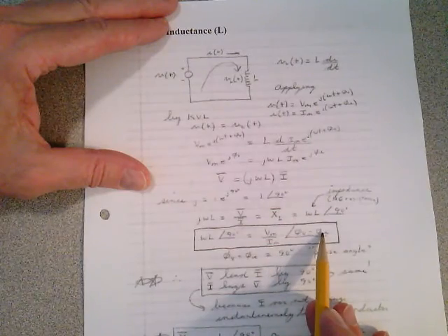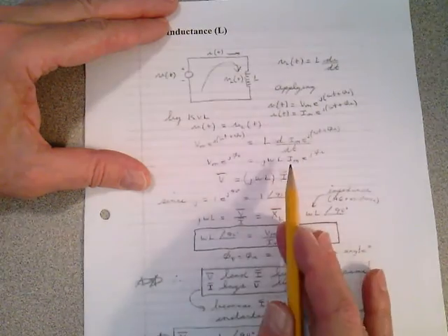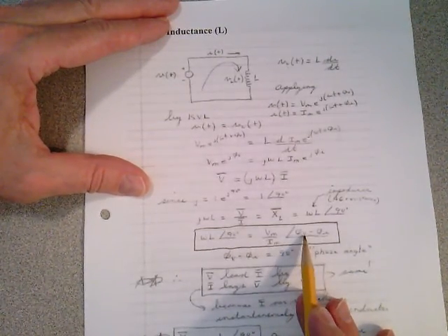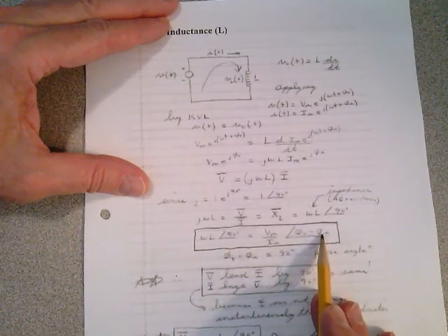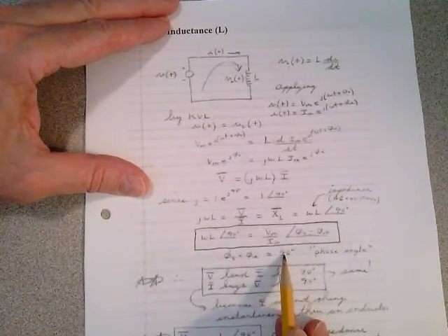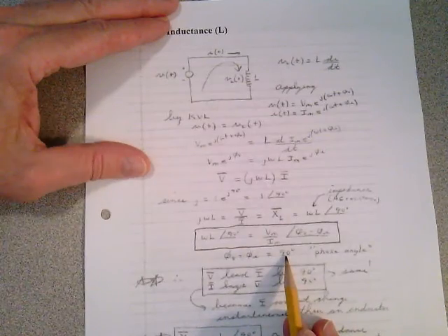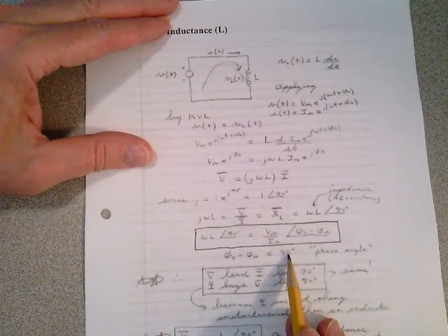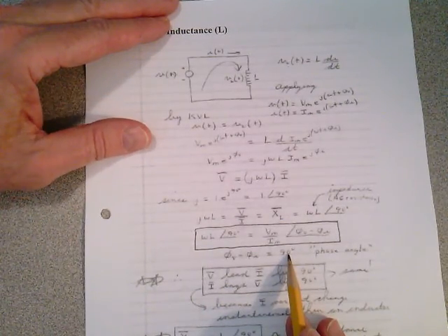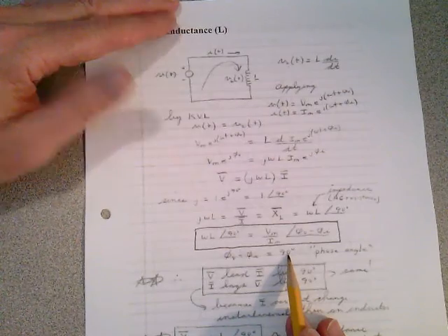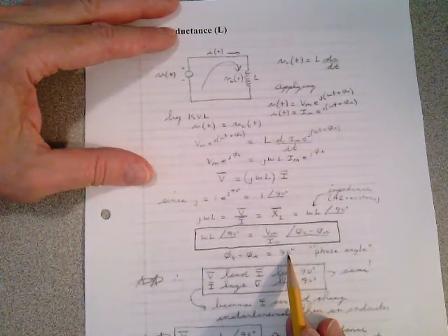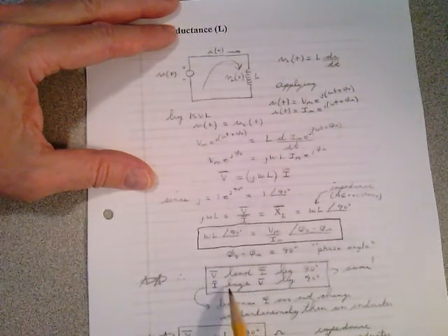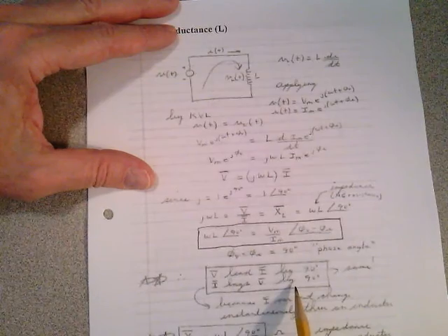phi sub V minus phi sub I, when you take these steps and move them down. That tells you that phi sub V minus phi sub I has to equal 90 degrees. That's the phase angle, plus 90 degrees. We said if the phase angle was plus 90, it puts it in the first quadrant. Anything in the first quadrant was inductive reactive. Think back from a couple lectures ago. So by looking at this, the voltage leads the current by 90 degrees. Or you can say the current lags the voltage by 90 degrees, either one.